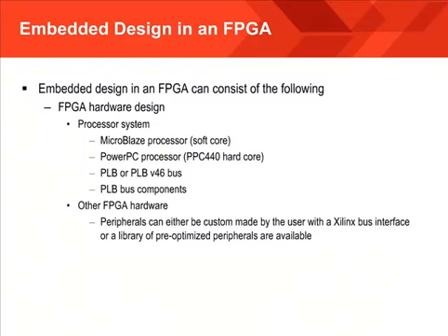A Xilinx embedded system can be nearly any computing system. It is typically single-functioned so that it is small and efficient. This is beneficial to FPGA customers because they don't have to purchase an expensive off-the-shelf component that may already have a large number of peripherals already added. The FPGA solution allows customers to add only the peripherals they need and build any custom peripherals they can't get from an off-the-shelf component. To help with design construction, Xilinx provides a library of verified peripherals that you can add to your system at no extra cost.